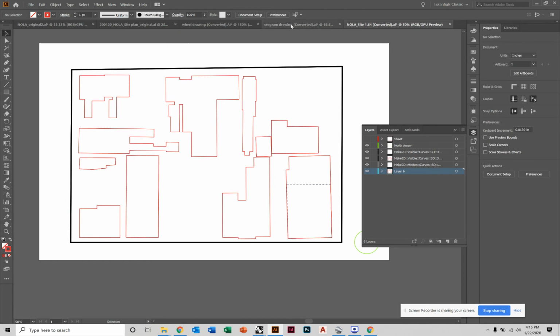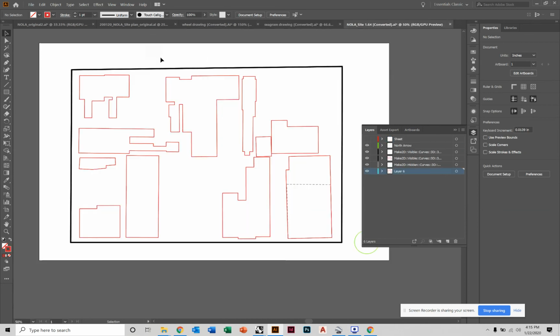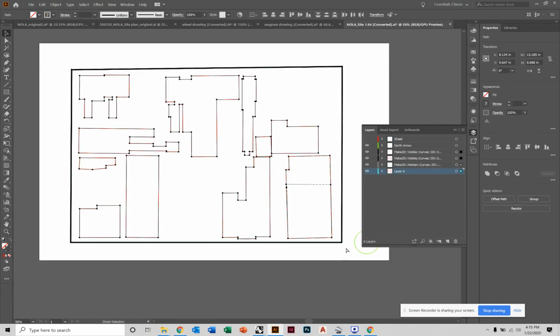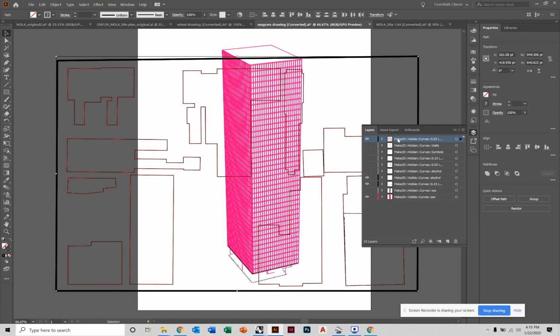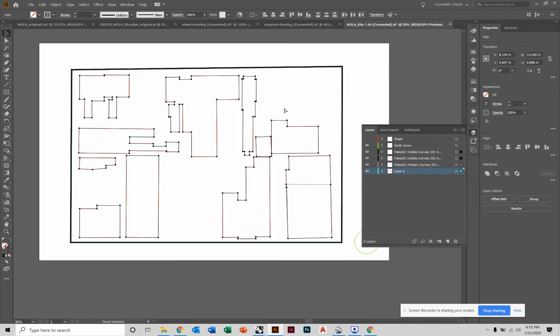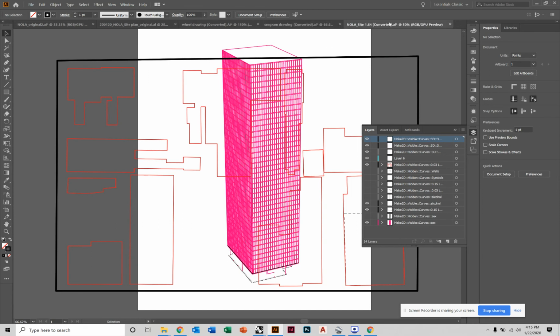So I have this drawing here, which I was going to go over, but we're not. I can copy all of this, Control C, go back here, Control V, and everything is on a single layer. But if I want, I'll just do Control C, Paste Remembers, Control V. Now it added the layers that came from that other file. So everything is separated. Saves you time.